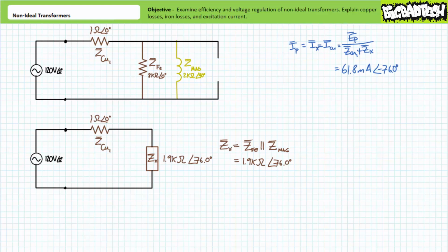Can you dig the heavy implications of this simple calculation? Transformers always draw current, even when they're not providing power to a load. Now, before you freak out about this, take note of the large lagging phase angle, characteristic of a reactive element that merely exchanges reactive power with a source and largely doesn't consume real power. This being said, it's not lagging by a full 90 degrees. We might expect consumption of a small amount of real power.